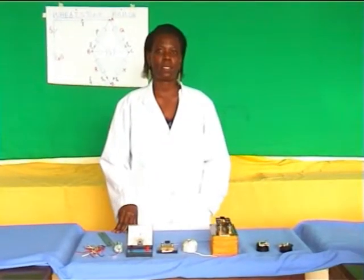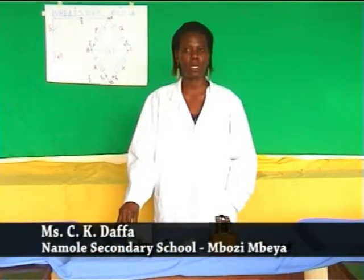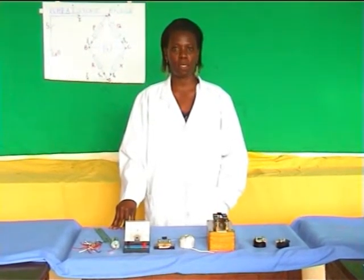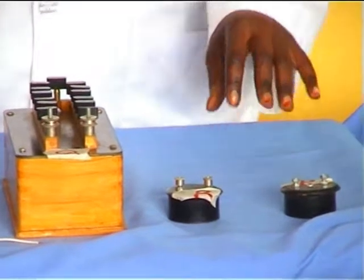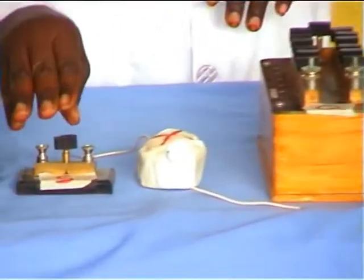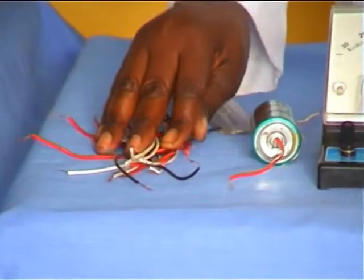Any conductor that is used to provide a known value of resistance in a circuit is called a standard resistor. The primary purpose of the resistor is to control the amount of the current flowing in the circuit. The aim of the experiment is to determine the unknown resistance by using a Wheatstone bridge. Requirements: 3 standard resistors, which are resistor P, resistor R, and resistor Q, unknown resistor X, switch, galvanometer, dry cell, and connecting wires.